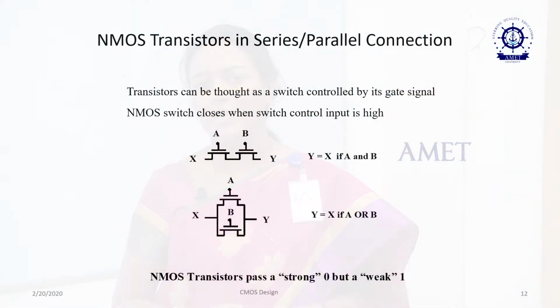And you can see if the input voltage is 0, output voltage will be high. Similarly, if the input voltage is high, output will be 0. This shows the basic structure of one CMOS inverter. Whenever the input voltage is 0, output will be high due to the current conduction of the PMOS transistor. And also you can see the characteristic curve, that will be the inverted output.